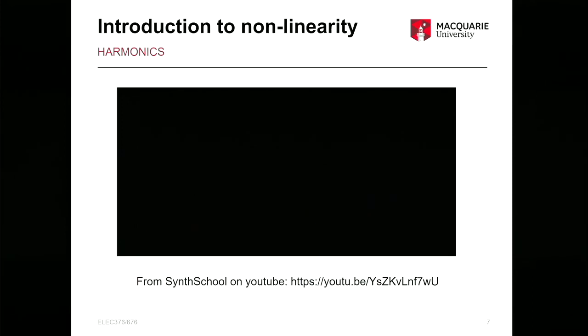So the fundamental frequency will have one gain, the higher harmonics will have different gains, right? So the output will be completely distorted. It wouldn't look like a square wave, it would look like a really different shape. So we use a sine wave as an input for many systems because that's the simplest to analyze.